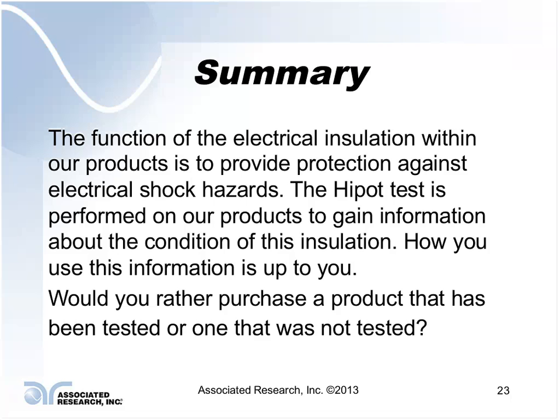Arc detection may not necessarily be considered a breakdown. It could be just a single momentary flashover. Some standards say single momentary flashovers are to be ignored if they don't result in an avalanche of current that would trip off the current detector. So there are a lot of different reasons.